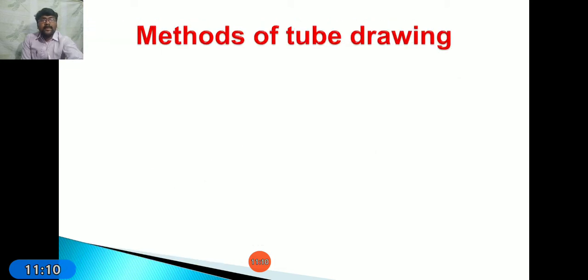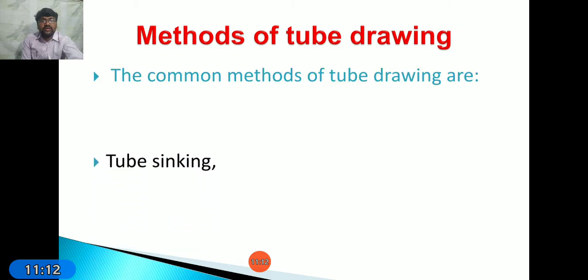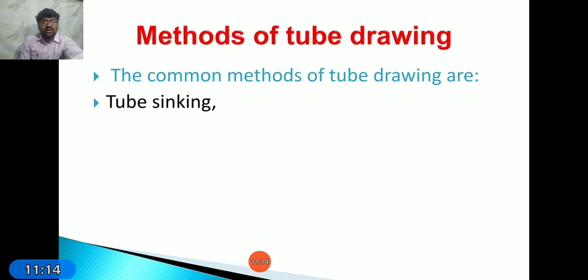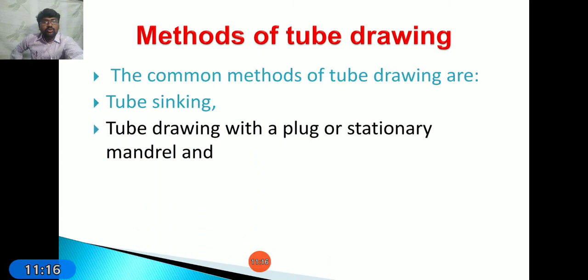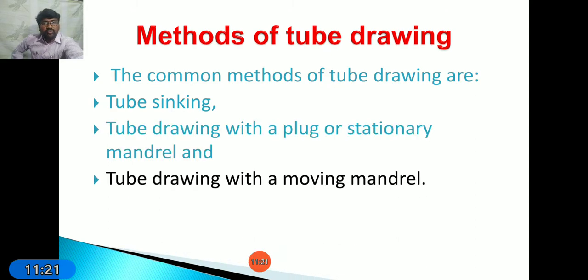Next, coming to methods of tube drawing. Here the common methods are tube sinking, tube drawing with a plug or stationary mandrel, and tube drawing with a moving mandrel. These are the different methods we can use in tube drawing.